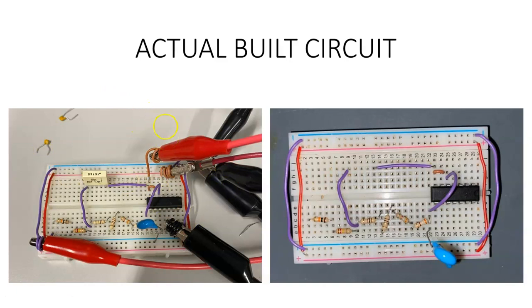So you use channel 1 and channel 2, where in channel 1 you ground the negative side, and in channel 2 you ground the positive side. So you have to obtain a common ground for both channels. Once you get a common ground for both channels, now you have the positive and negative 15V, which you can now connect to your op amp right there.